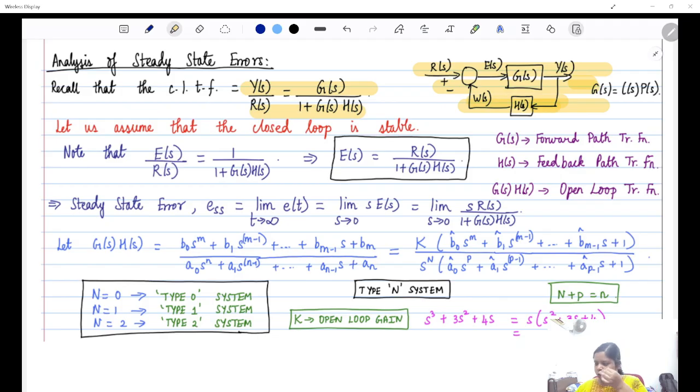Where you have G(s) to be the plant, H(s) to be the sensor, Y(s) to be the output, and then W(s) is the output signal which is being taken as feedback from the sensor. E(s) is the error, which is derived from the difference between the reference and the output that is being sensed, to give real-time feedback. This we already know. So we just have to manipulate this equation to find out some relation between reference value and error.